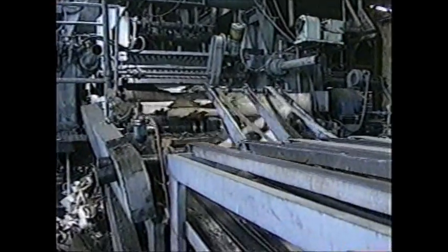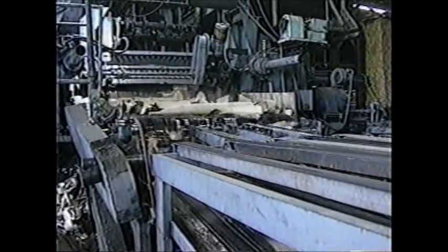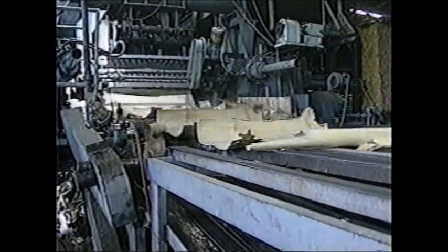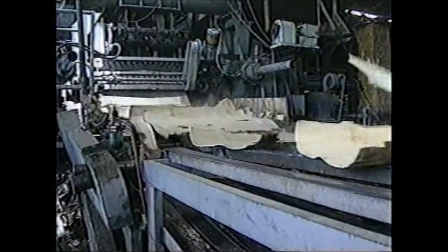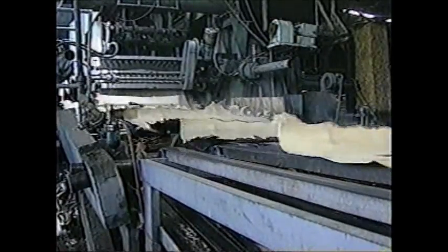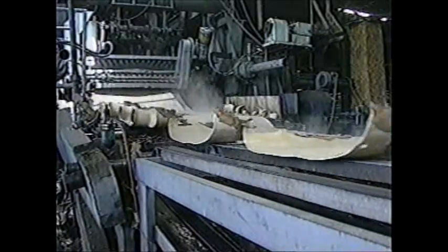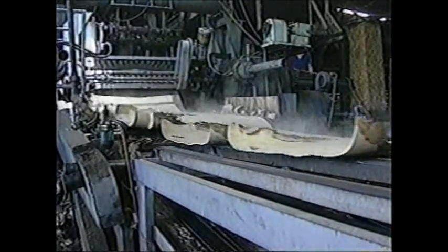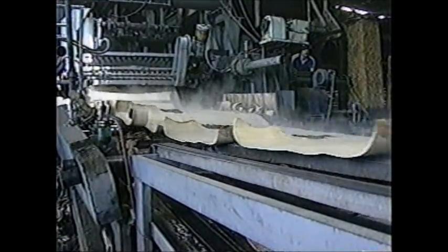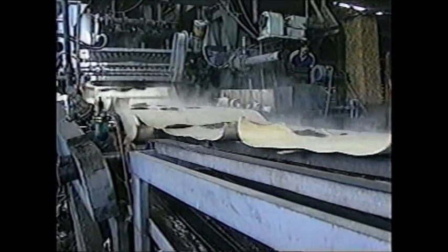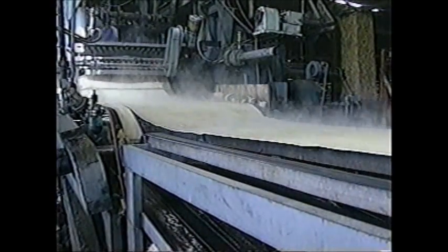The early roundup veneer is riddled with defects, such as holes and tears resulting from debarking. Since the log is not a perfect cylinder initially, the veneer is not continuous or full width. The early roundup is diverted into a chipper for use as fuel or in paper manufacturing.